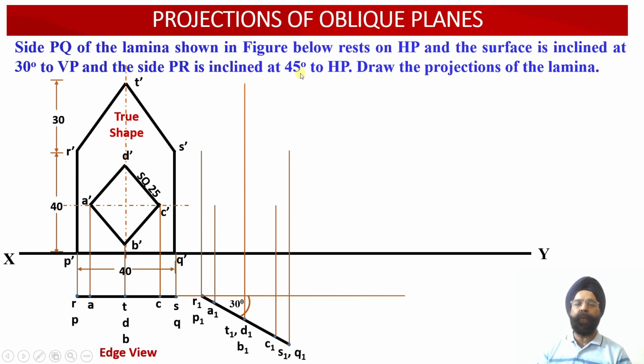So the intersection points will provide us with the location of the elevation projection points corresponding to this apparent shape view. So here we can see point T1 dash has been obtained by virtue of the intersection of the vertical projector line drawn through the point T1 over here and the horizontal projector line drawn through the point T dash from the previous elevation projection view.